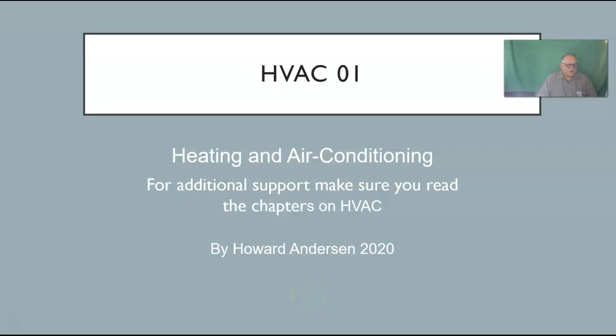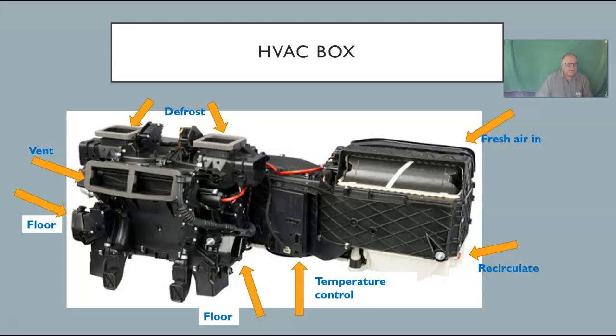In this video, we're going to be covering the basics of HVAC. In this box that you see on here, we're going to be looking at the box from the right to the left. So at the top right, they're showing you fresh air in. That's actually going to be drawing air into the vehicle right in front of the windshield. As you're moving down the road, there's going to be a high pressure area that's going to build up in there. So the faster you go, the more air it's going to push inside.